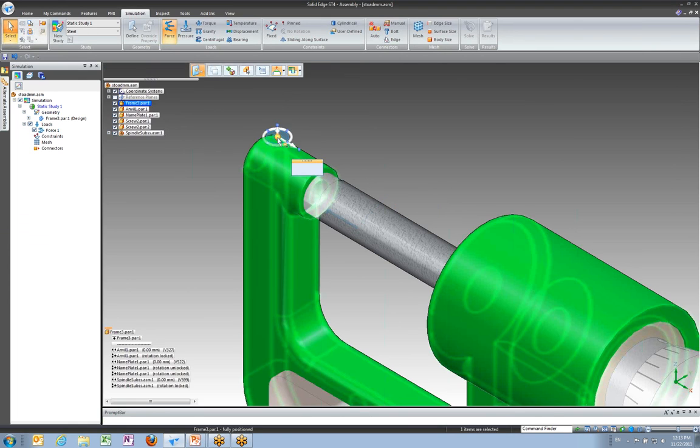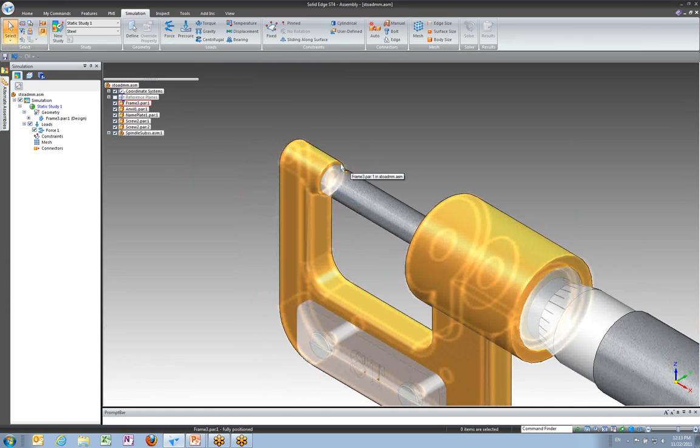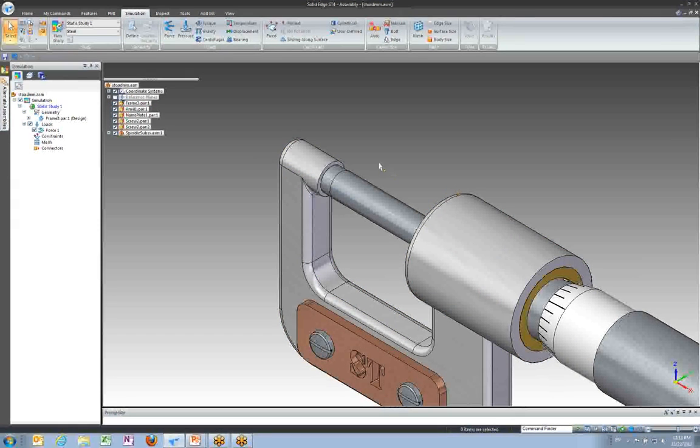So what else do we need other than force? Well, the next thing we need is constraints. Right now I'm pushing on this face, but the program doesn't know, are you pushing this along so it's traveling away? How is this thing constrained?